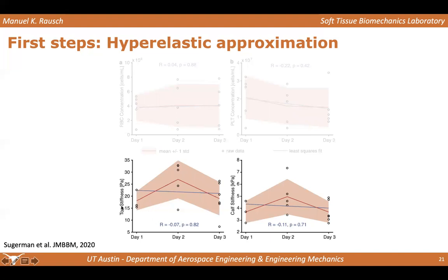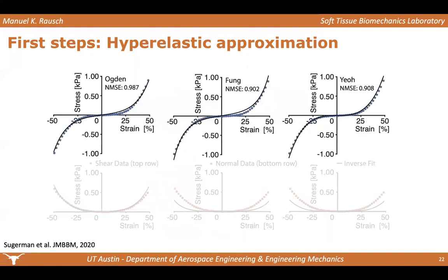But regardless, you see that at small strains, the stiffness is in the Pascal range, which is incredibly low. And at larger strains, it's in the kilopascal range, which still is very low, but obviously stiffer, reflecting that nonlinear behavior. And so ultimately, we recognize that to understand the fracture of a complex hydrogel under large deformation requires numerical models, right? There's almost no other way to understand, say, quantities like fracture toughness without having models that allow us to decouple other dissipative mechanisms from that of surface creation.